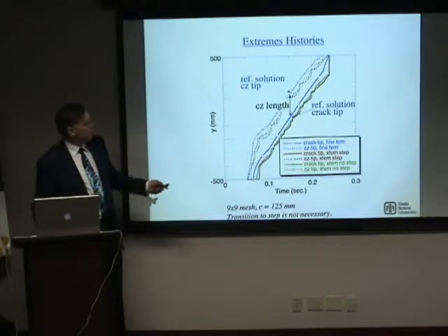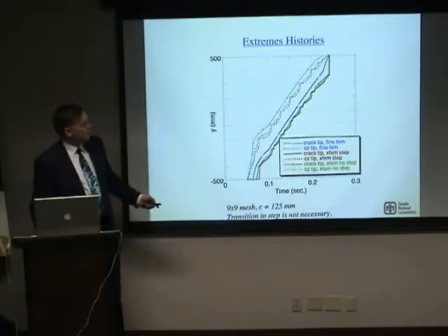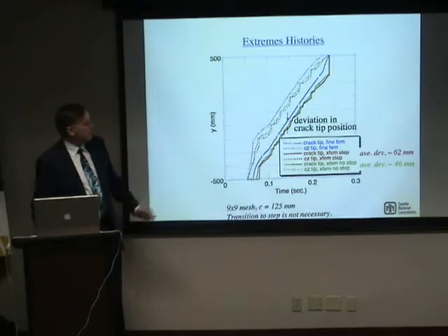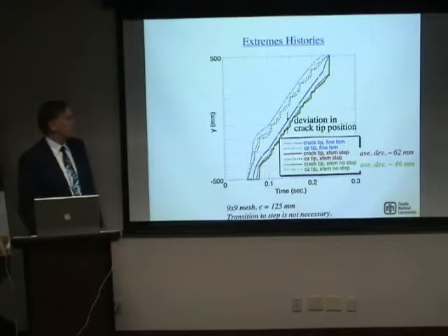And then in a similar manner, I'm showing two results here for XFEM. One of them switched over to Heaviside in the wake of the crack, and the other one did not. The difference at a given time between this reference solution and our approximate solution I refer to as the deviation in the crack tip position.